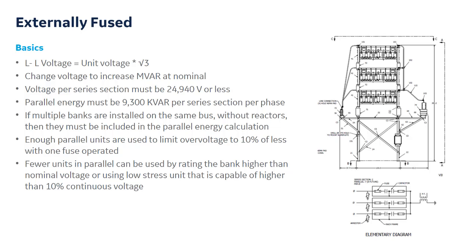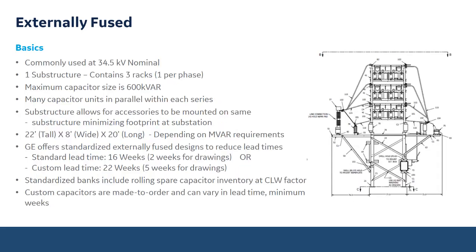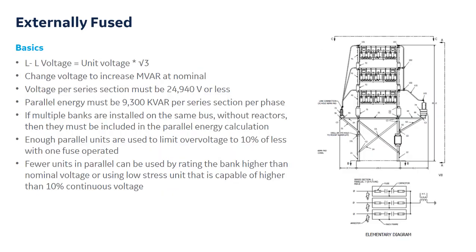The downside of going to a 2-series capacitor bank here is each rack does need to be insulated, where before each rack was tied in together. Now you're adding insulators, which is increasing the cost of your ultimate capacitor bank.